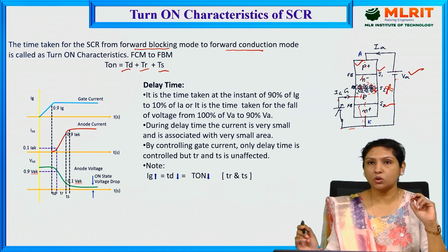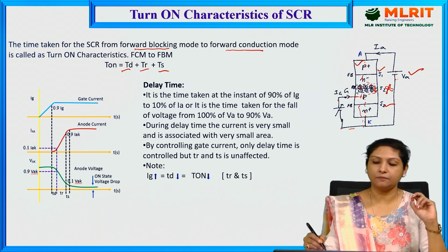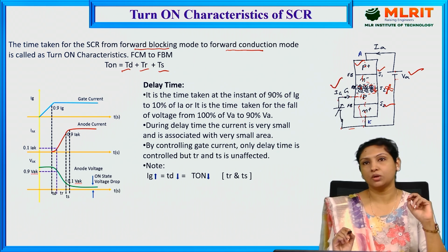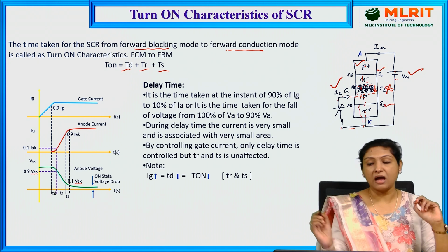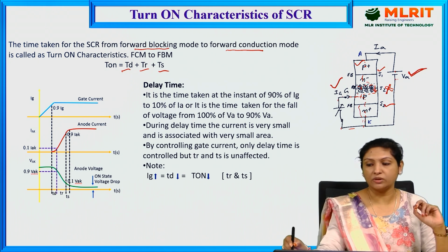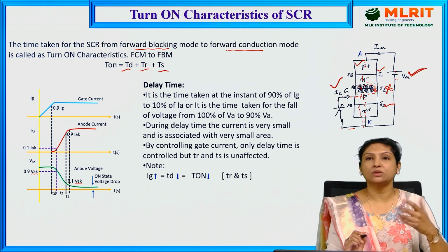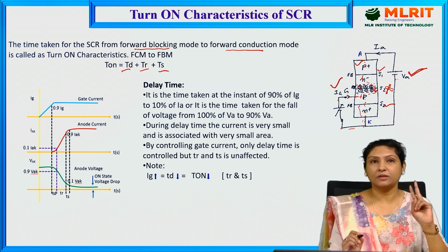So the turn-on time of SCR depends upon the gate current magnitude which we have applied, as well as the forward anode voltage which we are applying. It depends upon these two factors. So let us see.